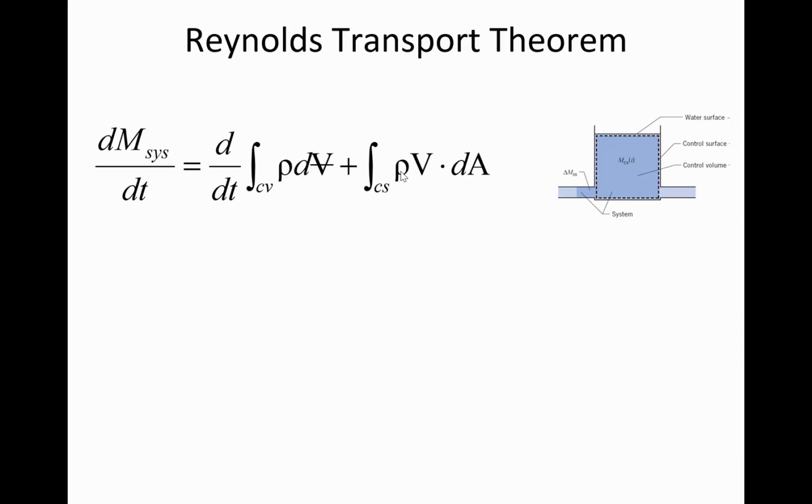So last time in class we started talking about how m dot, the mass flow rate, which typically has units of kilograms per second, is a way of tracking the mass in the system and its location over time. So what the Reynolds transport theorem says is let's consider these control surfaces and do an accounting. Let's do an accounting of the flow in compared to the flow out through those control surfaces, and then also let's consider the change over time inside of the control volume.